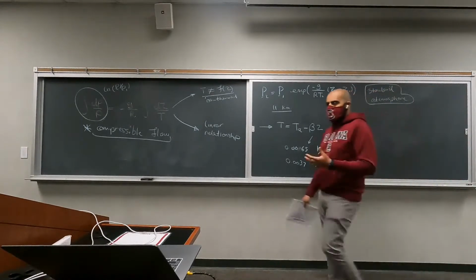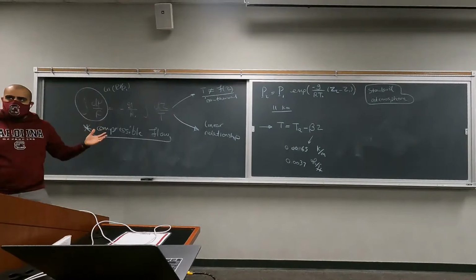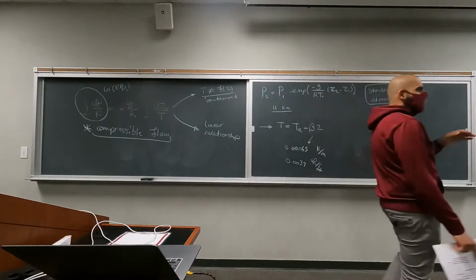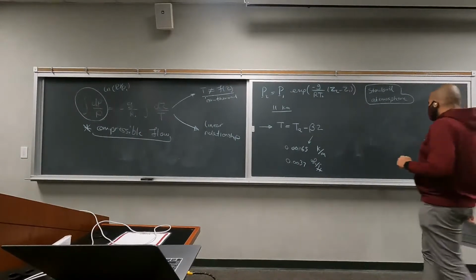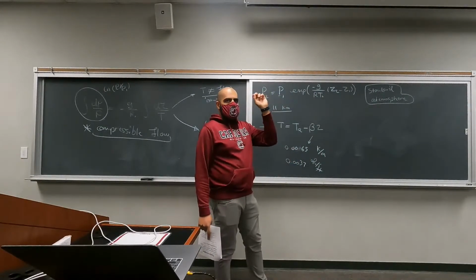So this standard atmosphere is going to give you the value of pressure at 20 kilometers above the surface of the Earth, right? And that is supposed to be the same value throughout the Earth. It doesn't matter if you're in China or in the United States, right? You should get the same value when you are 20 kilometers above the surface of the Earth. This is not a true assumption. The idea is we have standardized the whole thing. The whole idea is to come up with a standard value. So we are essentially measuring an average value for that pressure or temperature at that specific height.